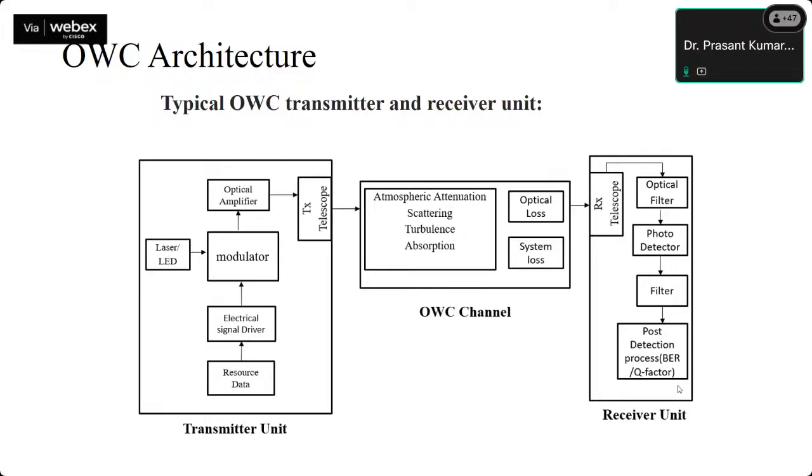Then we need a modulator. We are not going with direct modulation systems. The reason is that if you use direct modulation, there is a greater chance that the laser may malfunction after a short period of use. To extend the laser lifetime, or to make the laser more reliable, the best option is to go with an external modulation scheme. So we need external modulators.